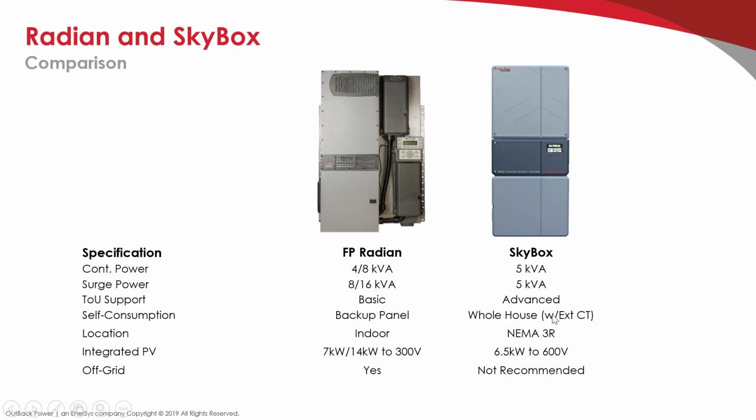With Skybox, it has an external CT that can go on the utility side of the main service panel, and it can check and make sure that nothing's being exported. So not only your backup panel is being used for self-consumption, but the main service panel as well.